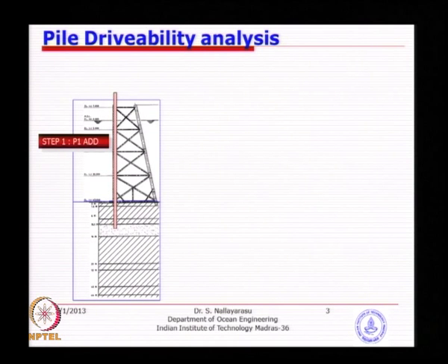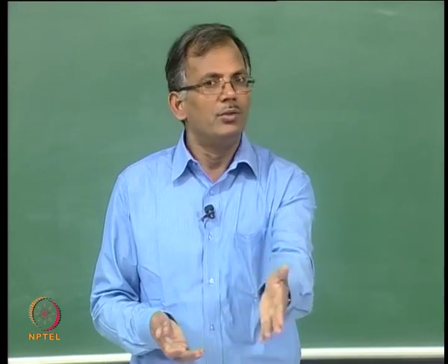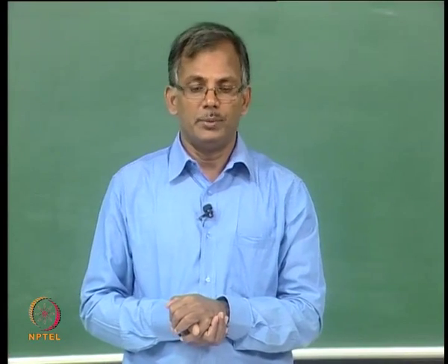If there is no stopper and the soil is weak, the pile might actually disappear. In some cases, if you are very certain that you do not need a stopper, because you know very well that the soil at the top is very strong, maybe not clay but sandy material, then you can go without a stopper. So, the pile is placed and is not going anywhere, but that assessment has to be done carefully.